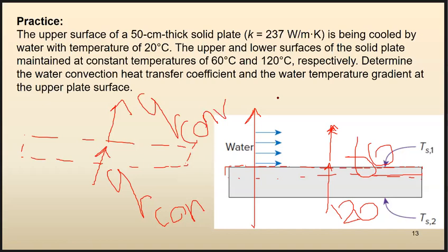This is a steady state situation. It means nothing changes versus time. So we don't store more energy than we already have inside our control volume. Whatever we receive, we need to release. Whatever we gain, we need to give to the surrounding. So whatever amount of conduction is transferred toward the inside of this imaginary volume must be equal to whatever is leaving in the form of convection.